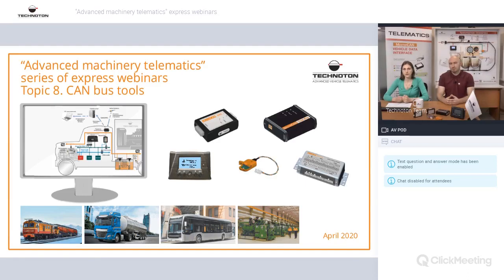All those types of MasterCAN devices have indicators on top, and the indicators are really useful to see that data is coming during your installations. Indicators are provided for power, for interfaces, and for each input and output signal. It's really useful to rely on those indicators to be sure that your wires are connected properly and you install the device in the electronics of the CAN bus in the proper way.